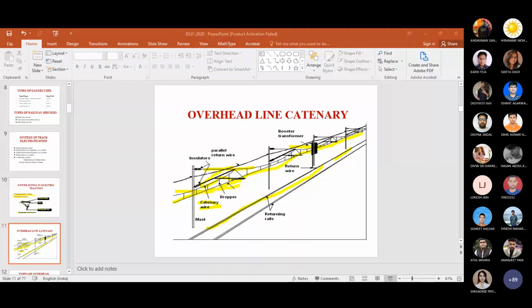For a DC machine, initially there is a chance related to the back EMF, so initially high resistance is required. For what? Suppose your terminal voltage is 230 volts, just as an example, and the size of the motor is more than 5 kilowatts. The motor armature resistance values are very small, in the range of 0.5 ohm.